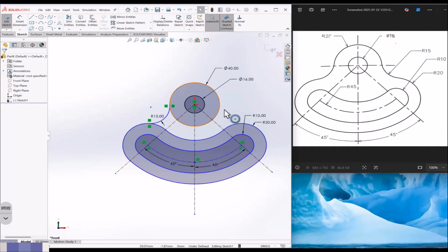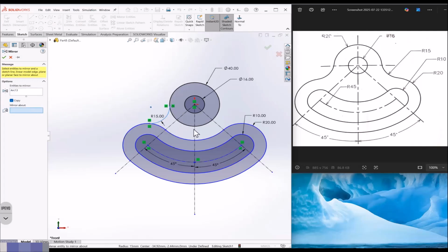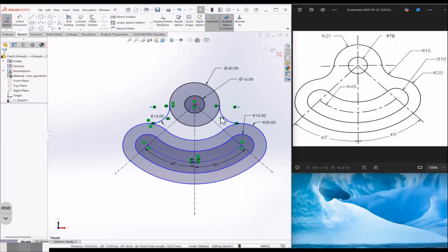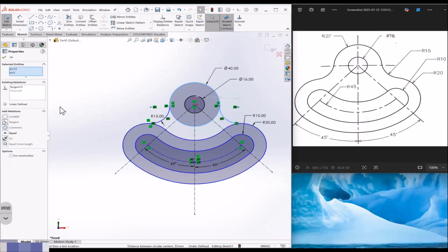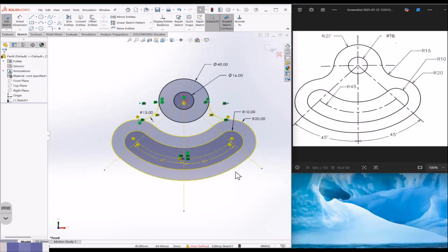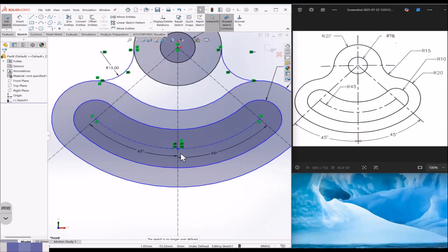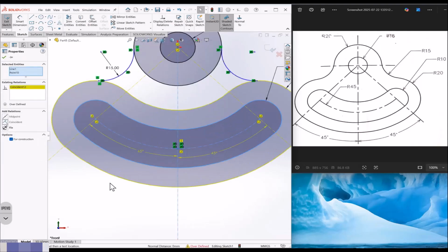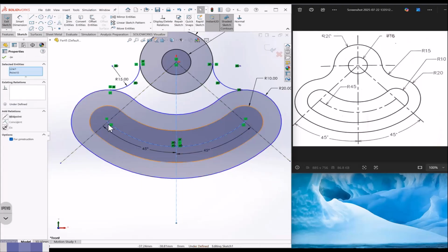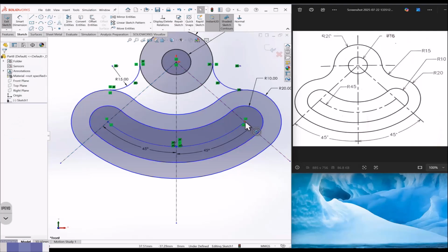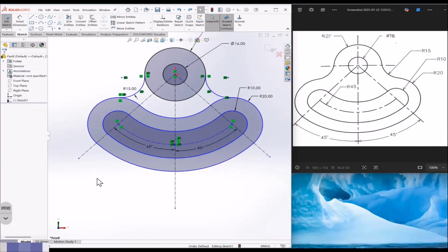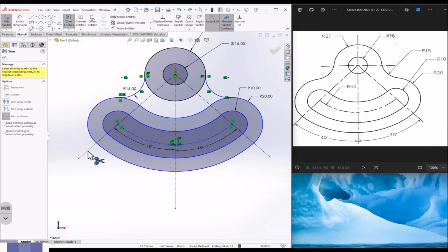Now we'll just mirror this to the other side. We'll go to mirror entities, select this and mirror about the center line and do OK. Make here also that to be tangent. This to be also tangent. Okay, now it's taking over dimension when I'm defining one tangent. Let's delete the tangent initially. Now make all things coincide with this. It's again over defined. Let's see. We have to cross verify everything. This and this to be coinciding. And let's trim the extra line.